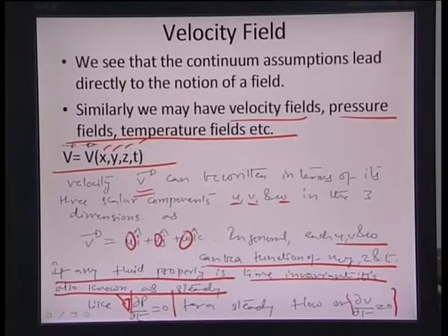However, in flows which are heated up, this may not be the case, because the density would keep on changing from the cold surface more towards the hot surface in touch with the fluid in question. And so, as we will see later on, especially in microscale fluidics, we hardly need this component of heating, and we can do away with the energy equation of the Navier-Stokes equations because of that reason. So in microfluidic situations, mostly we use time invariant flows. So, dV by dt or dP by dt or d rho by dt, or any other property with respect to time, does not really vary at all within such domains.